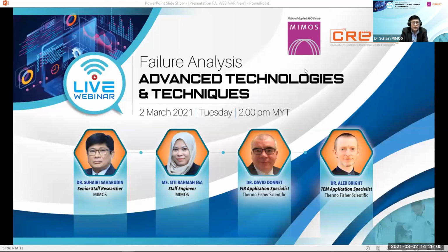Okay, this is something that is very tricky because each of the FA tools has its own strength, and it is always a case of whether it really suits the particular analysis or not. But there are times when we have to balance between fast lead time and cost. So the only limitation that I can foresee with respect to the tools that we have, in three categories: electrical, physical, and material, is the cost. You can have a fast lead time by performing cross-section using FIB, which is costly, or you can have a slower process, which is cheaper, using mechanical polishing. So that's the sort of constraint that you have whenever you want to choose between the various failure analysis equipment.